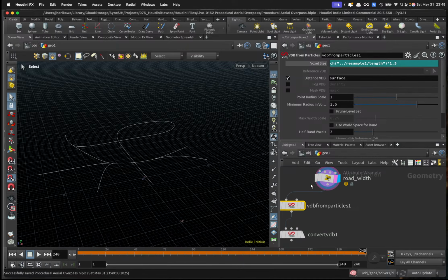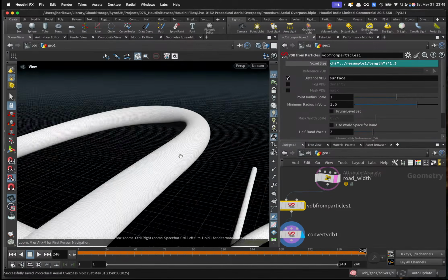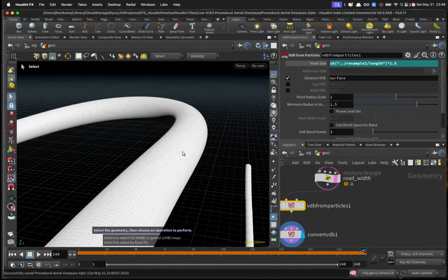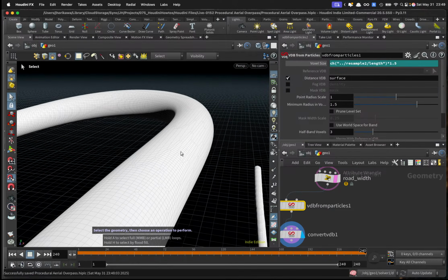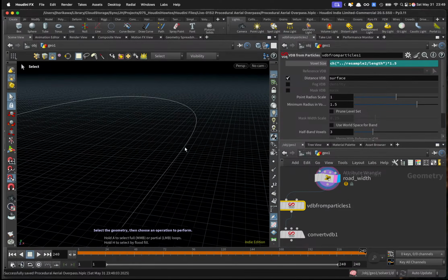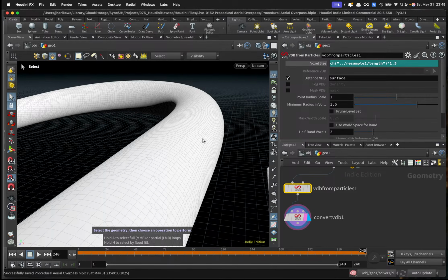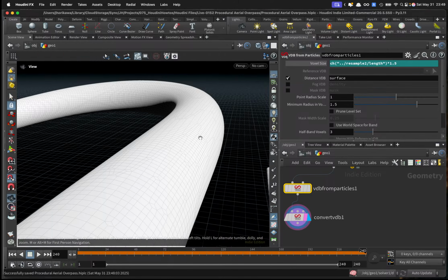So what I'm going to do is, for each point from this pipe geometry, I'm going to search for the closest point, for example like this point, to the road curve, and just copy the height of the closest point position on this road curve, and apply that height to each of the points found on the pipe, which should give you some flat surface all over the place.